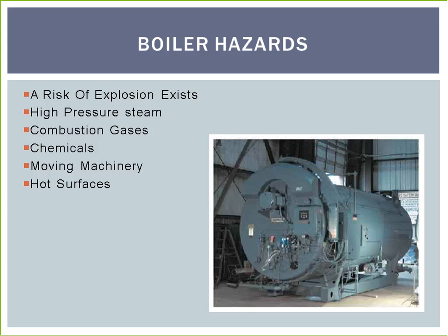Number 3 is combustion explosions. These can be a result of gases which build up and an ignition source ignites the gases. This can happen inside the boiler or outside. There are safety devices in place to avoid these situations, and we will discuss these in the following slides. Steam pressure is the 4th one, which is excessive steam that builds up and exceeds the design pressures of the vessel. There are also safety devices to prevent this.